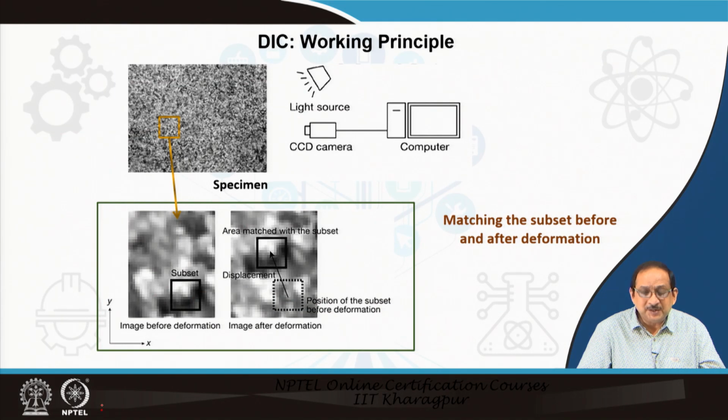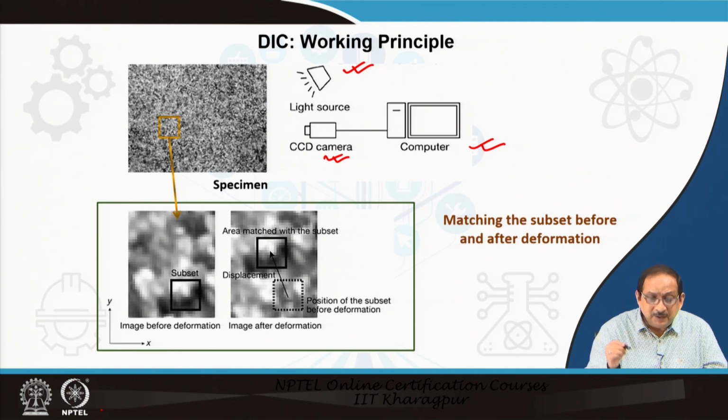Let us briefly discuss the working principle of the digital image correlation technique. As indicated earlier, you can see that there is a white light source, and digital cameras to record the deformation of the speckle pattern, connected to the console or the computer.